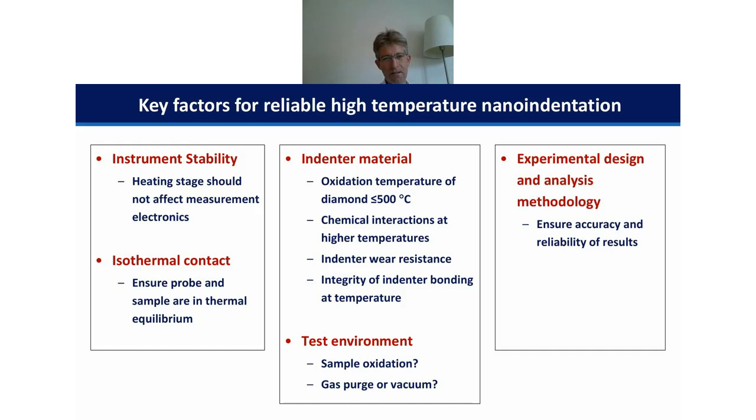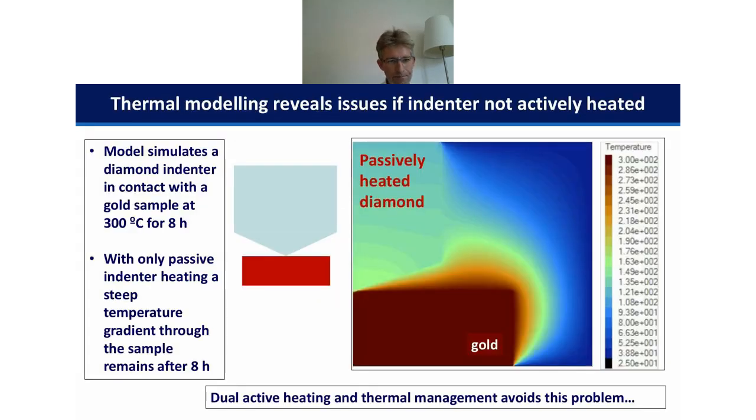And lastly, we need to understand that even if we accurately control and account for thermal drift, the deformation mechanism that we get may be more dominated by time-dependent deformation than analogous results at room temperature. That can even be the case for systems like hard coatings, where you typically wouldn't assume there is any time-dependent deformation, and where you can design your experimental loading history and your analysis to mitigate these time-dependent deformation approaches.